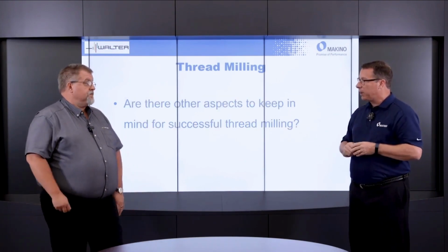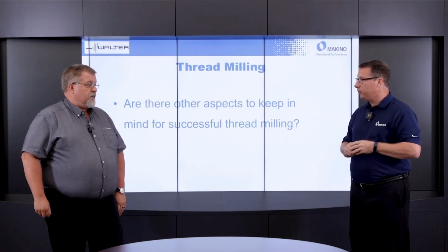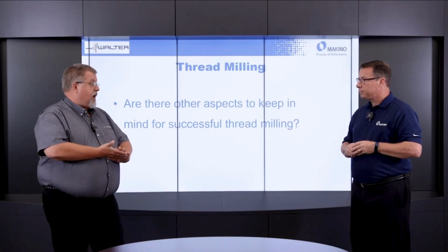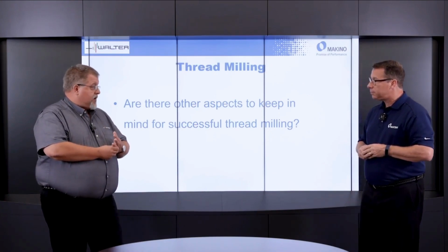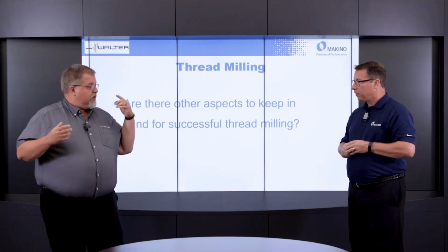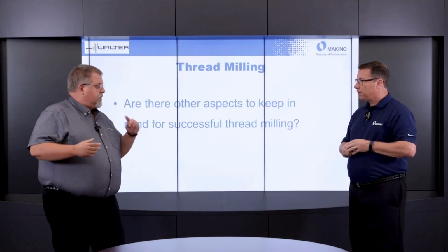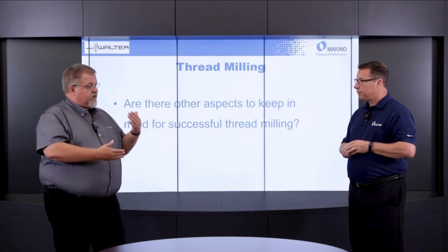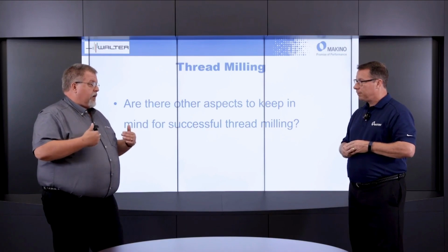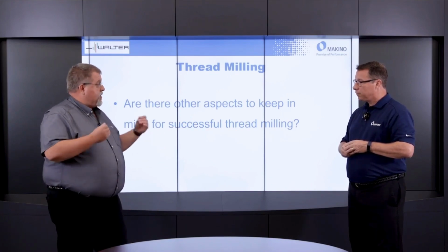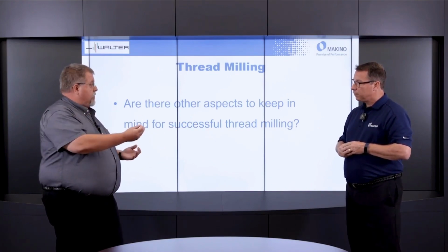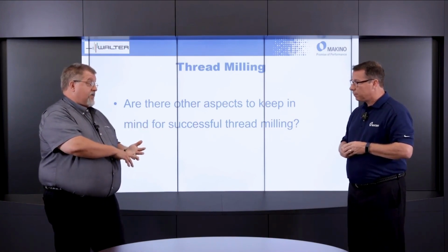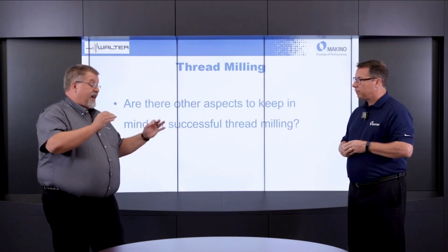Any other aspects, Brian, to keep in mind to have success using that thread milling process? Making sure you pick a quality tool and you get the programming right. There's a lot of different strategies out there about whether we want to do conventional thread milling or climb milling process. Do we put a spring pass in there? Don't we? As an example, we have a software where you can put in your application and it'll suggest the correct thread mill and the correct process. And at the end of it, it'll actually give you the program too.